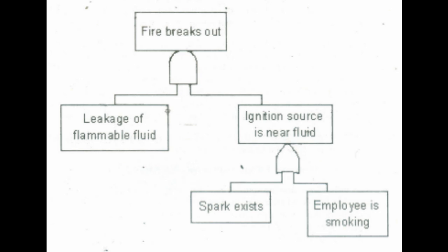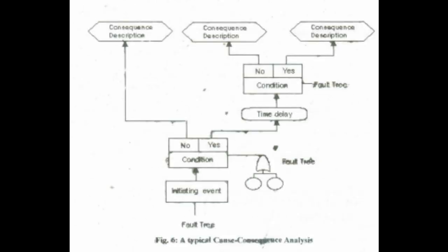3.5.2.2 Event tree analysis. Event tree analysis is a method for illustrating the sequence of outcomes which may arise after the occurrence of a selected initial event. This technique, unlike fault tree, uses inductive logic. It is mainly used in consequence analysis for pre-incident and post-incident application. The left side connects with the initiator, the right side with plant damage state. The top defines the system's nodes, dots call for branching probabilities obtained from the system analysis. If the path goes up at the node, the system succeeded; if down, it failed. ETA has seen application in the nuclear industries for operability analysis of nuclear power plants as well as accident sequence in the Three Mile Island 2 reactor accident.